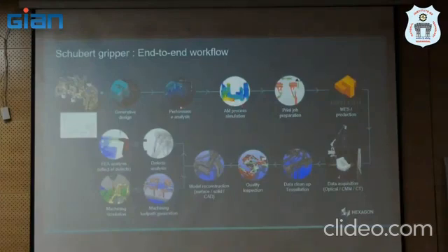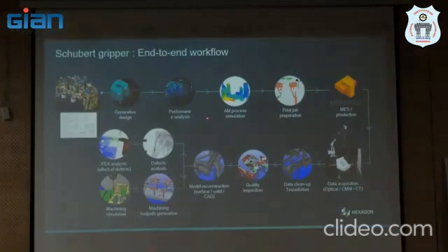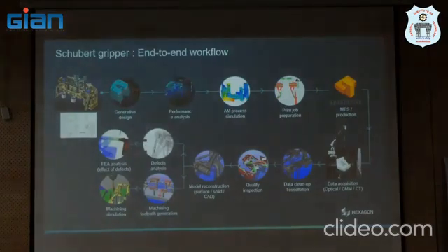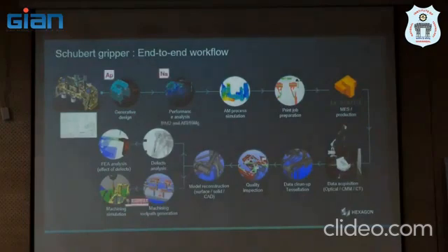Now we are talking about only material change, but you can ask me about changing the printing direction and the support structure, which can also affect the final part. So we have a lot of variables throughout the cycle which need to be taken care of. The best way is to digitally validate with all these variables and print right the first time. That's the overall idea here.